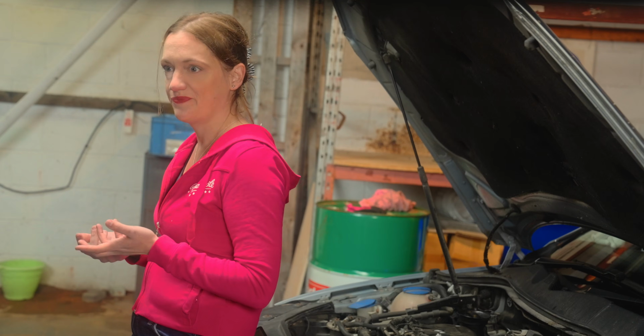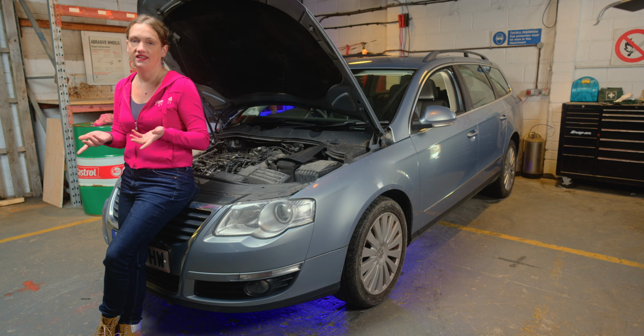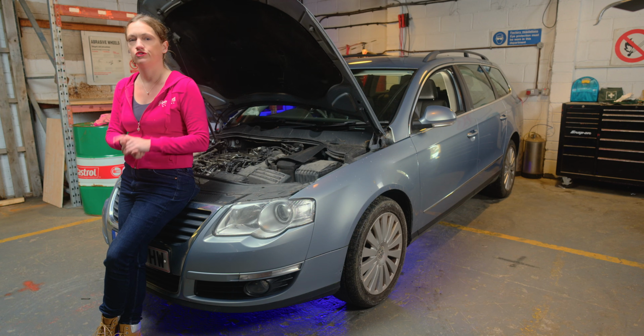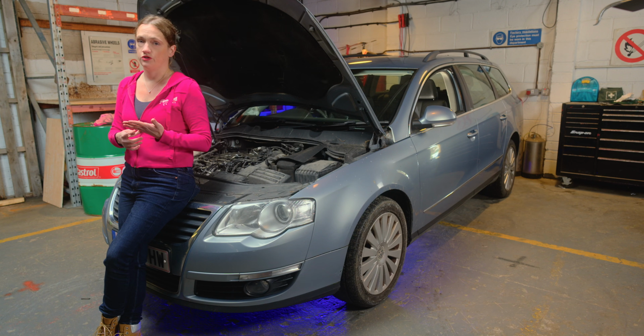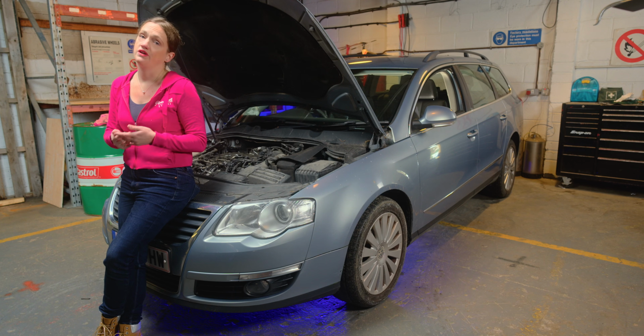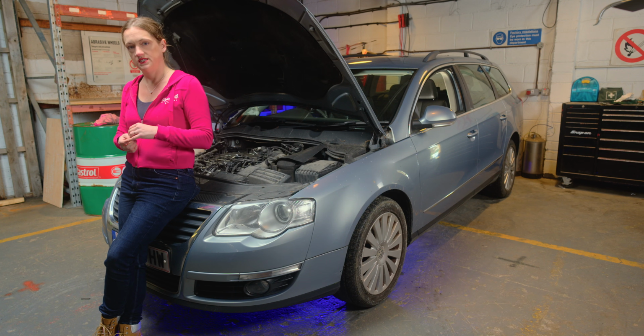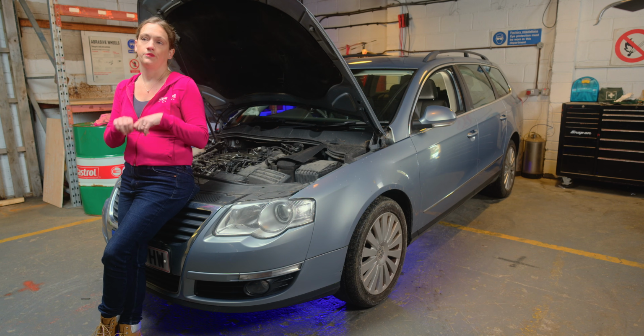Unfortunately, they get a build-up of carbon from the EGR system, and this causes the flap to become stuck, often breaking the gear or the arm that controls it. It may also be possible with the fault code we've got of open circuit that the motor is burnt out, or like on the Mercedes V6 turbo diesel, the wires inside have become brittle.